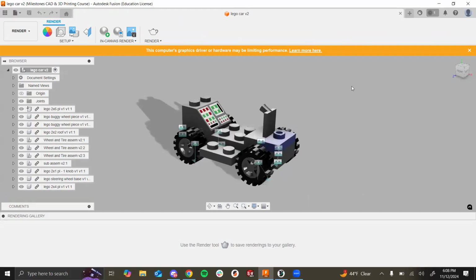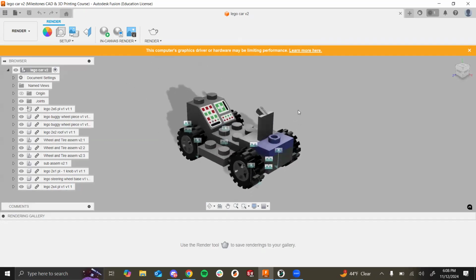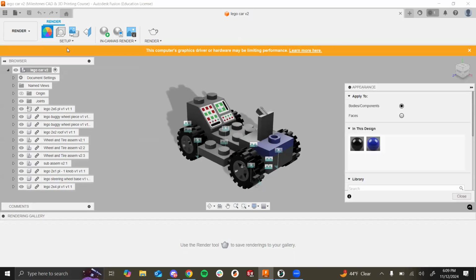You can see stuff is looking a little bit more shiny than it was before. You can even see there's a shadow because there's a light source on our model. So this is pretty cool, but it's pretty basic. For one, this part doesn't have all its appearances applied. So all those gray bits you're seeing earlier are now just gray. So if you wanted to add appearances, if you didn't do so before, there's this wheel up here that you can open up and it should be just like before if it opens.